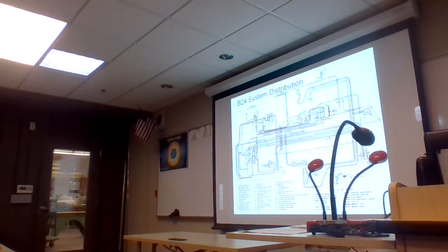Compare that with maybe something like this. That's a picture from a B-24 aircraft, a Liberator from World War II. Just a few things were operable hydraulically in that aircraft. I think the brake system was, and I think that maybe landing gear and maybe a couple of things in it, but not too much. And so it's a very simplified system. They've got an accumulator in the circuit. They've got a few other things, maybe a pressure regulator. I don't think they even use variable displacement pumps on the very much simplified.